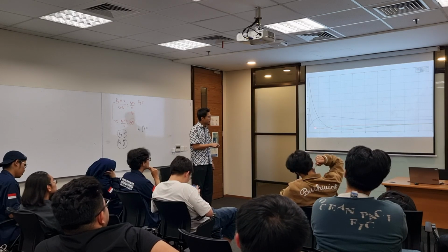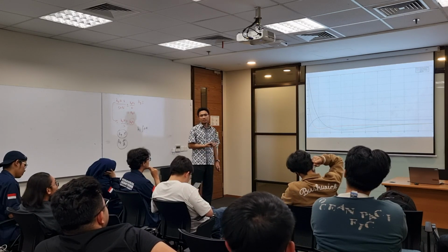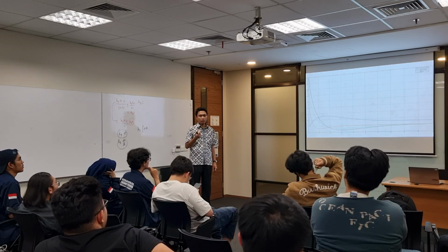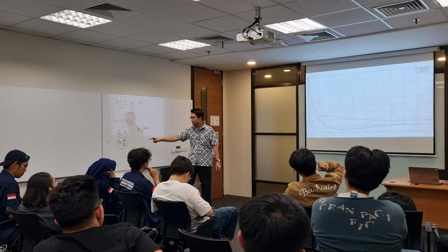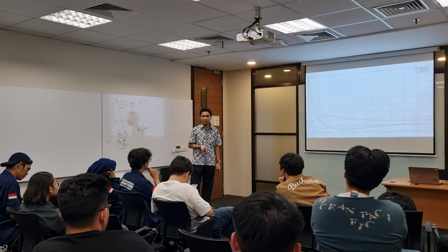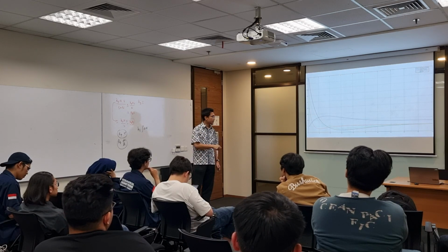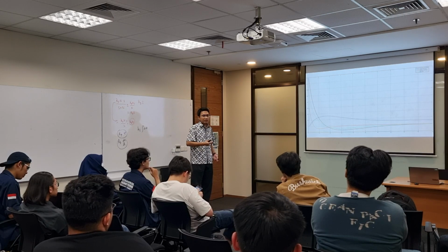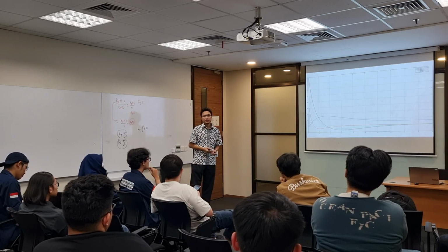Only the first 5 seconds, the derivative control action works, because the rate of change in the error is very large in the very beginning. After that it doesn't really help.